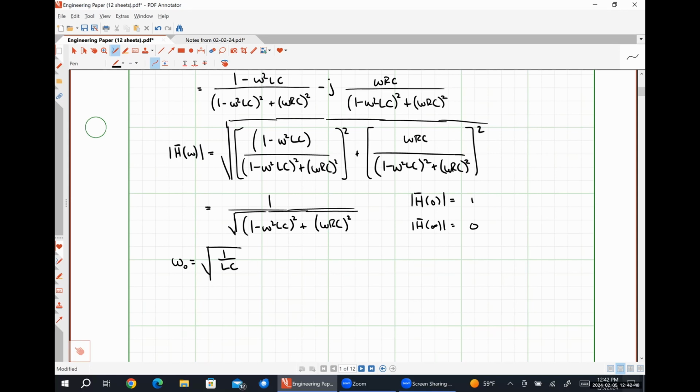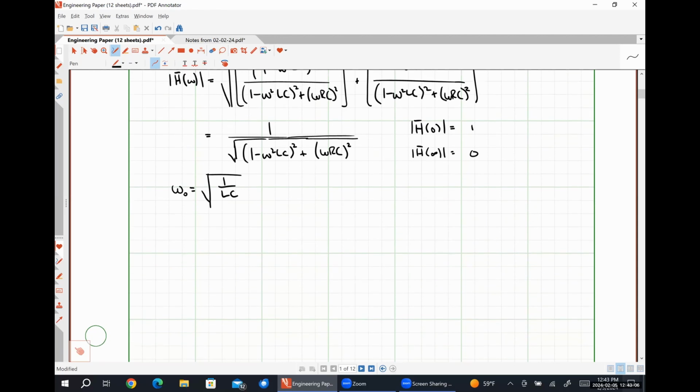So what I mean by that is when we looked at our first order filter, we saw that it decayed at a rate of 20 decibels per decade for our low pass filter. Now we should actually see it decaying at a rate of 40 decibels per decade because we have a second order filter. So it's going to roll off much, much faster, okay?